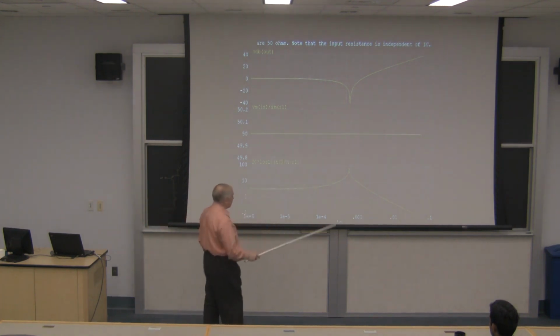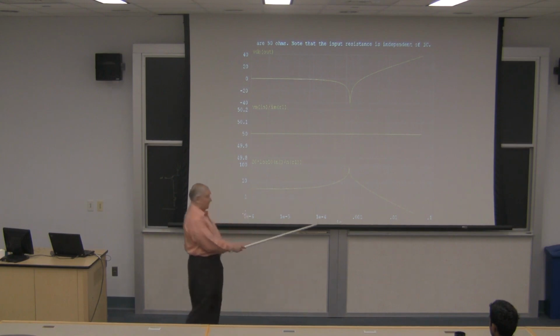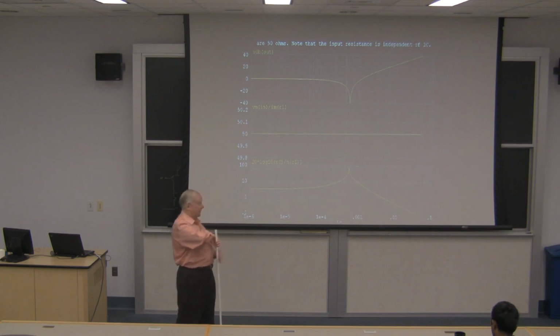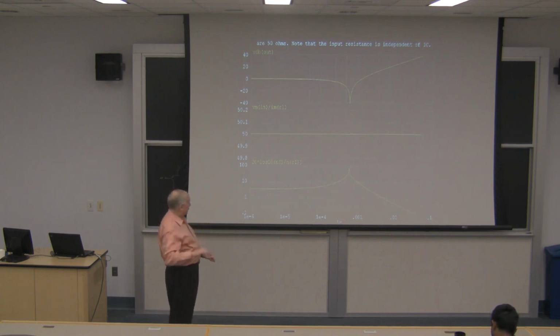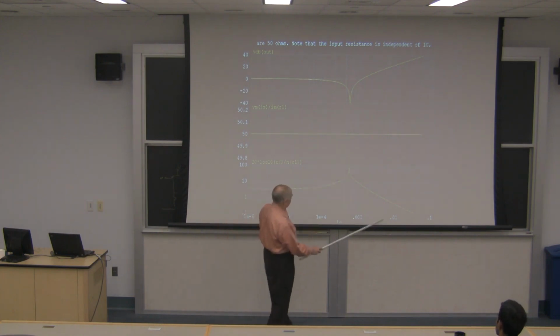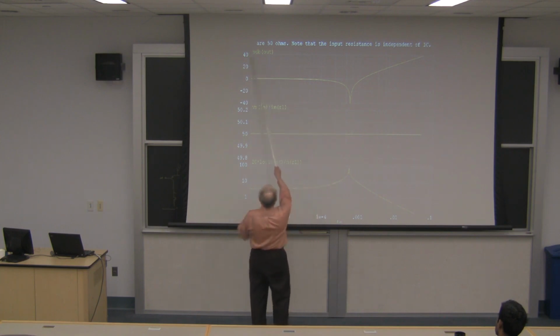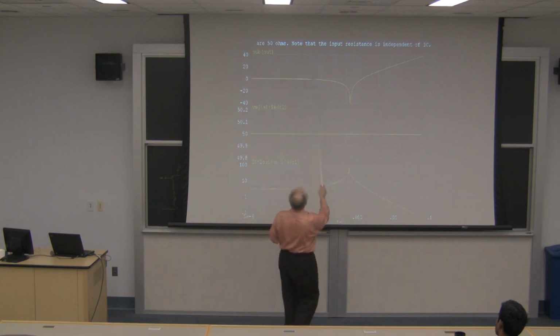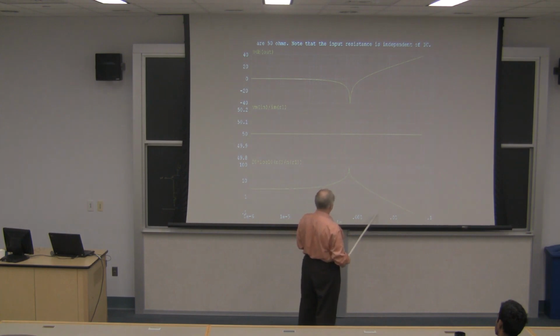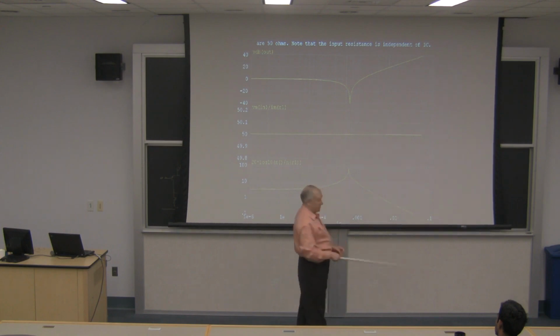You don't operate there. So you pop up a little bit, and this doesn't depend upon the process, doesn't depend upon the polarity of the device, doesn't depend upon a lot of things, but it's very fundamental. Anyway, so you move up the current a little bit, and at a certain point, you begin to get into favorable territory. So this is the voltage gain of this amplifier, and supposing we want a voltage gain of 20 dB, well, to get there, we need to operate at about 2 milliamps, and by that time, the noise figure has gone down to about 1 dB for an ideal transistor.